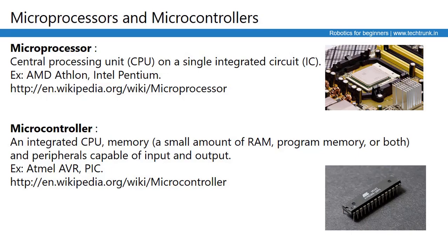And because of that, microcontroller based systems consume relatively less power compared to microprocessor based systems, wherein each device is connected separately and has to be fed separate power. Microcontroller based systems are also relatively cheaper in cost. So if you wish to design small-scale programmable systems, microcontrollers are preferred over microprocessor based systems.